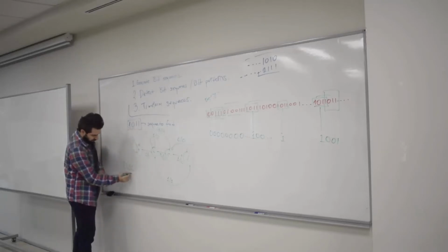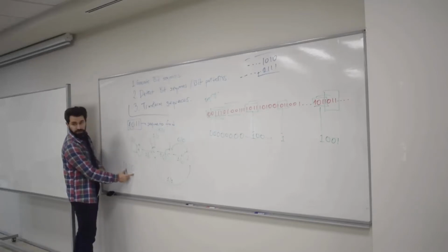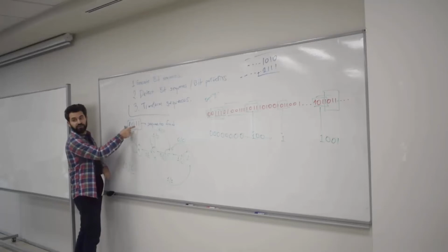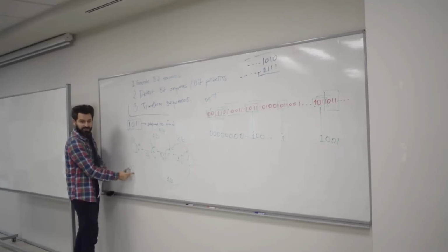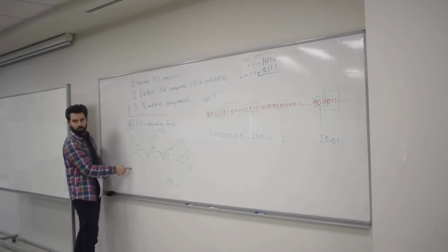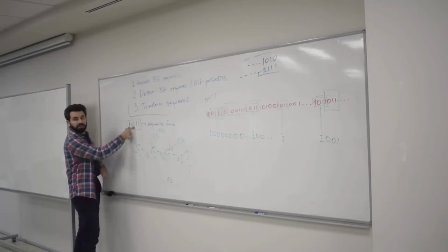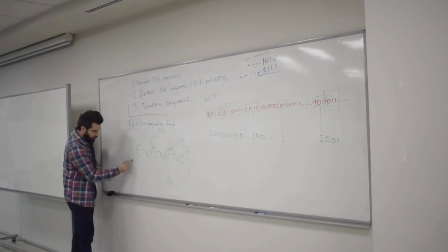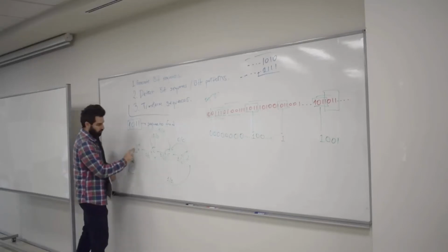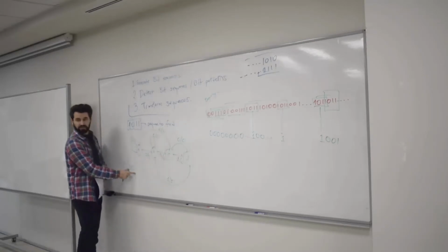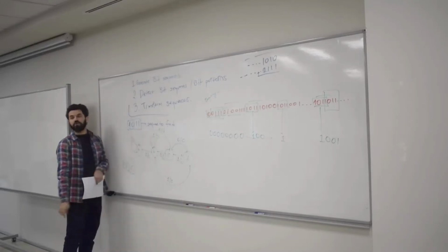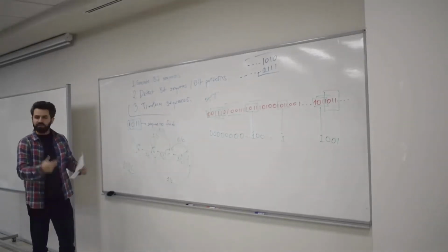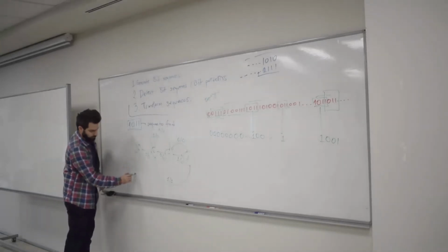But when I see these last 2 bits, 1, 0, not the 3 1s, because these 3 1s are not fitting in the prefix of the pattern that I'm looking for. That's why I'm looking for these 2 bits, okay? If I didn't have 1 bit, for example, I can start with 1 bit. Is this matching? No. Then I look for 2 bits. Is this matching? Yes. So I say, okay, I have already seen these 2 bits, 1 and 0, but that is already represented by one of our states, which is C. Then I should go back to C, because I already have seen 1, 0 in the input. Search for another. Yes, then you continue searching for other 1, 1, okay?